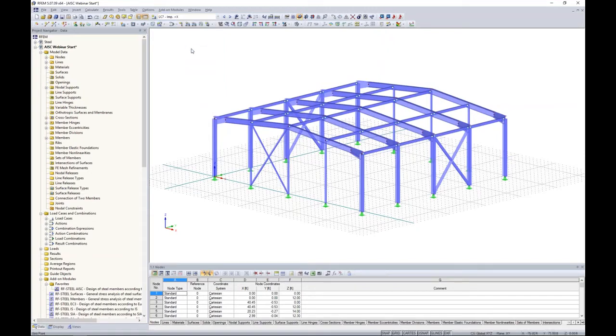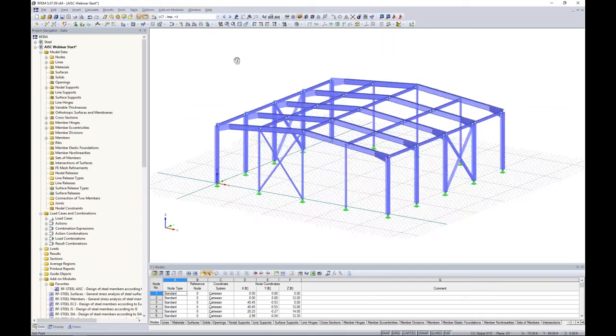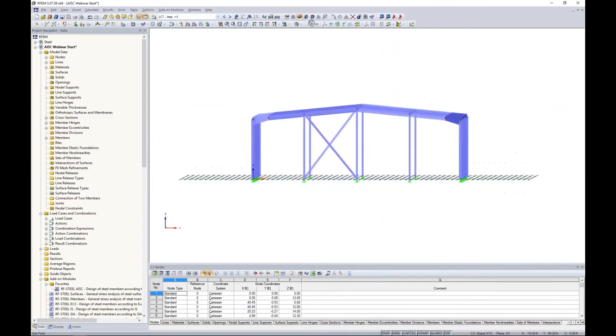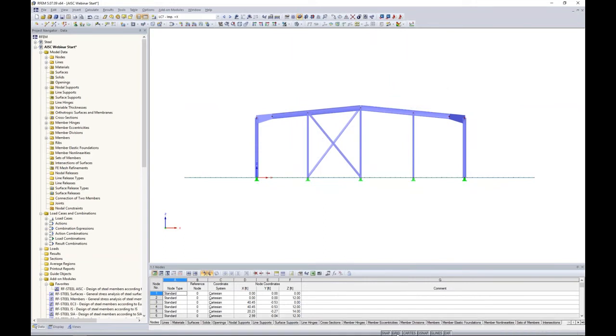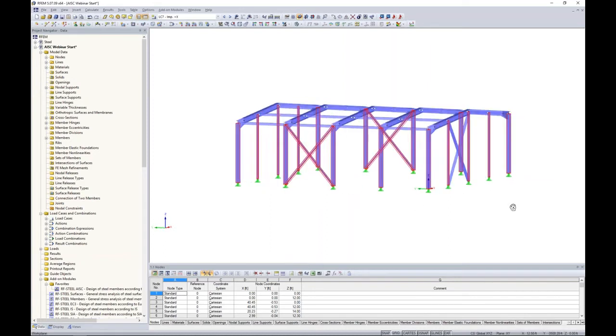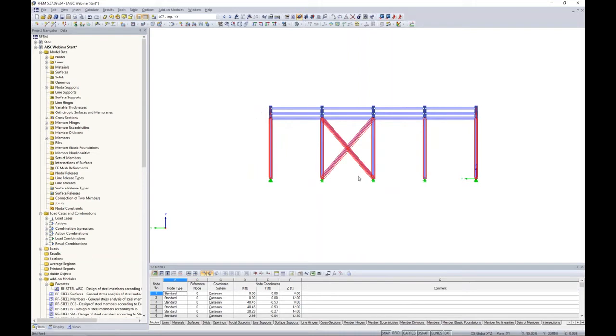So now that we have applied them to our load combinations, I want to select from my drop-down box here, imperfection in the X direction. Well, so I've applied them to my load combinations, but I haven't exactly applied them to my structure. So now we want to do so. As the code mentions, I only want to apply them to my column out of plumbness is really what we're looking at. So I'm going to highlight all of my column members, and if I hold down my control key, then I can unselect my braces here, just like what we would do in AutoCAD.